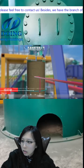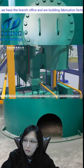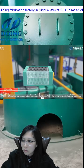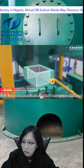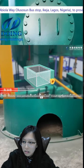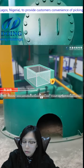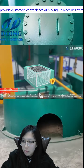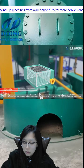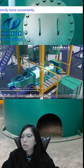The digester surface also has pipes filled with steam. It has the same effect, providing a comfortable temperature. And we all know palm oil is very sticky, and its fluidity is very bad. So if we don't give it enough temperature, enough heat, it may stick to other machine parts and break the chamber of our machine. It is damaging for our machine.